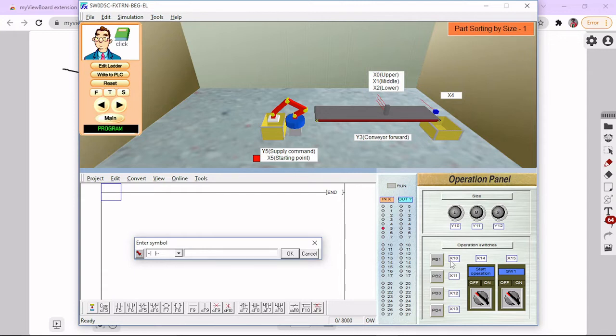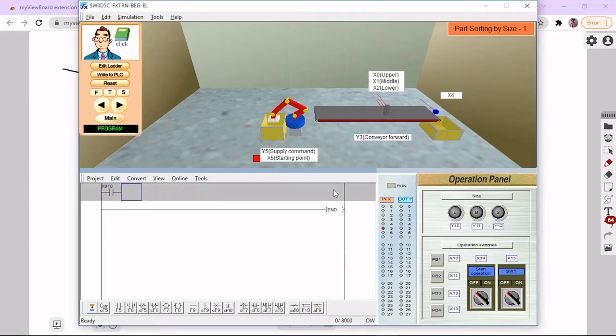you can see here that we have X10 on this first run. So X10 is an input device. What do I want to happen? Because every run must define a control operation. You have an input already, so there has to be an output on this run. The outputs that we have here are just three: Y10, Y11, Y12. So if I put an output device here, not an instructed output, in this case just a normal output, that's Y10, and I click enter.